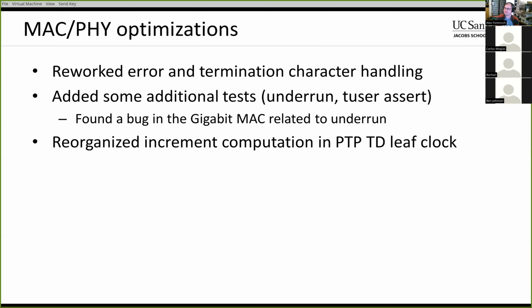And one thing that, coming from an embedded systems background and trying to write code that fits on a really small microcontroller, one of the things that you try to do is reuse variables or use as few variables as possible so you're not eating up a lot of stack space or a lot of globals or whatever. But using that same technique in HDL is not necessarily the best idea, because while you'll save a few flip-flops, you might end up using more LUTs.